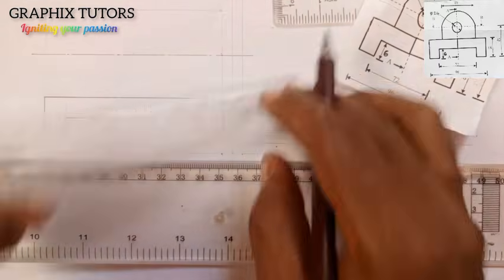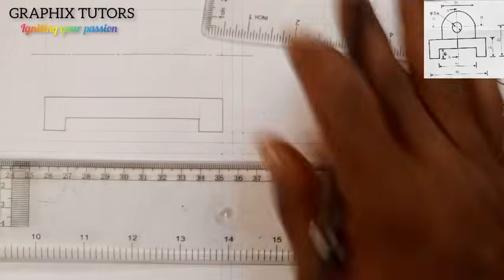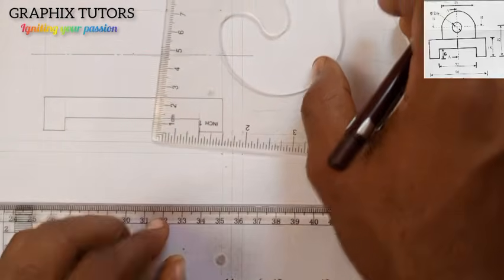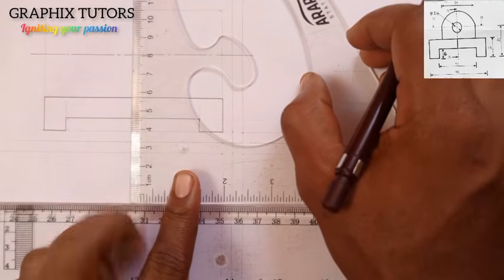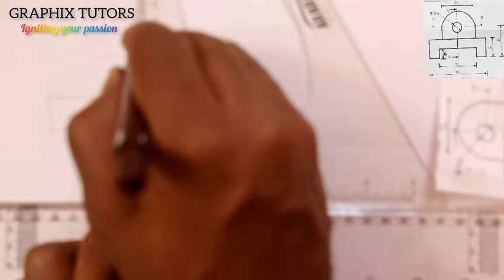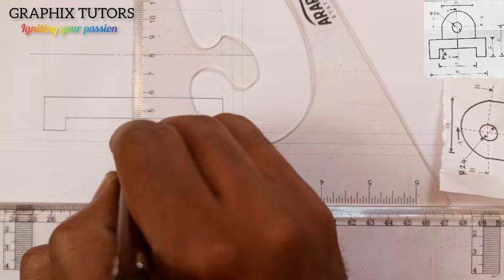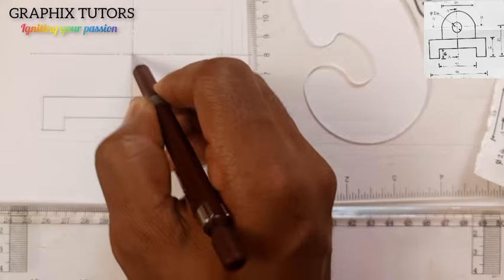So I'm going to use my meter rule. Now draw another center line there to show that is the center of the figure, because it's a symmetrical object. So at this point, I'm going to draw the center line, the long, short, long, short, long, short. You can see that? Let's put this way. So this is where they are meeting here.